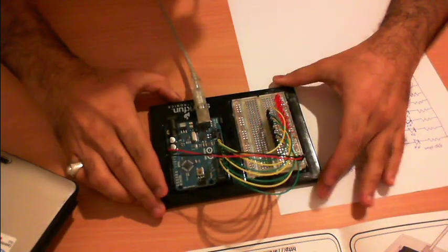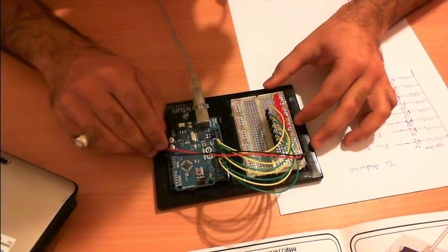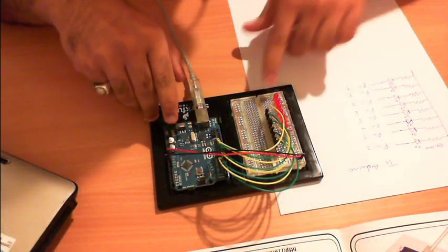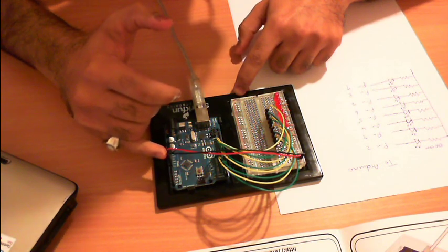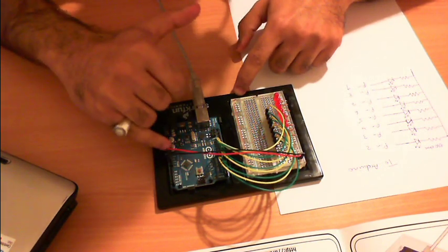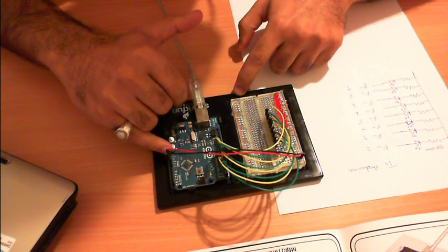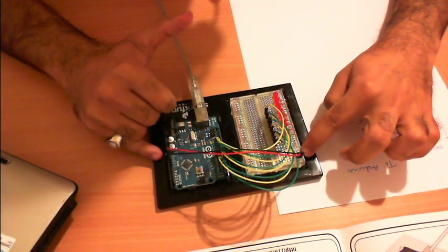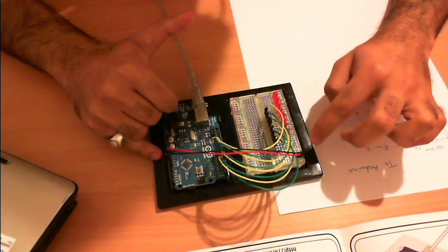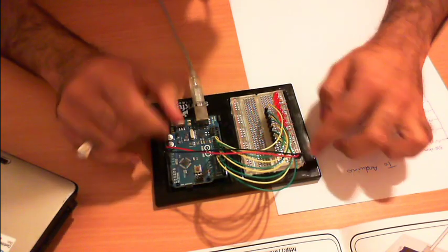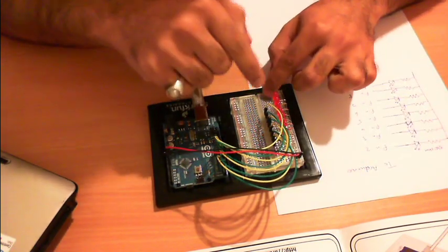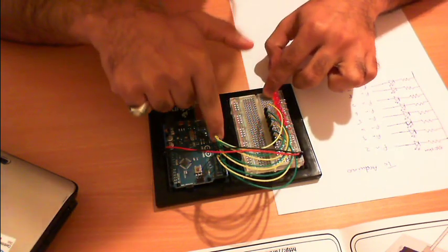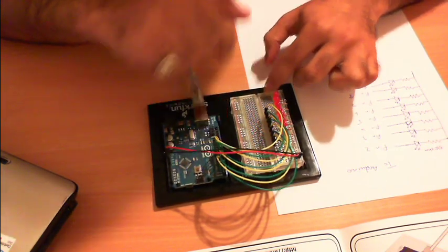Now I've wired the whole circuit up, and this is what it should look like. We've got our Arduino board on this side, and we've got the breadboard on this side. Now we have a positive and negative wire coming in from the ground and the 5 volts on the Arduino board. That goes into the positive and negative rail on the breadboard. For this circuit we will actually not be using the positive rail because each positive of the LED is actually connected to the pins on the Arduino board directly.